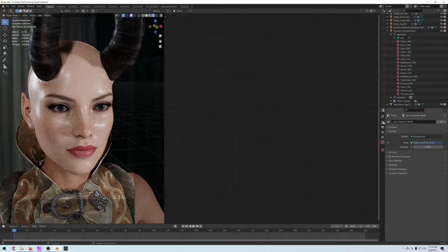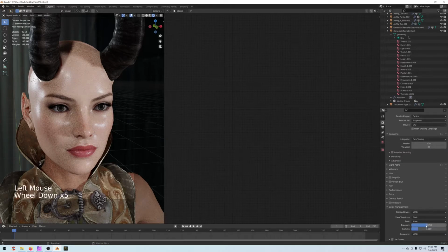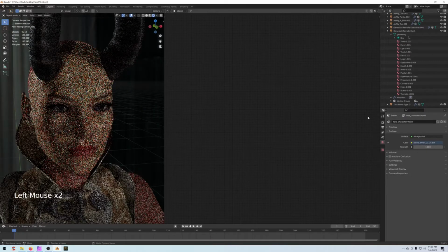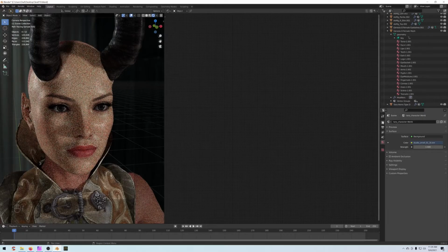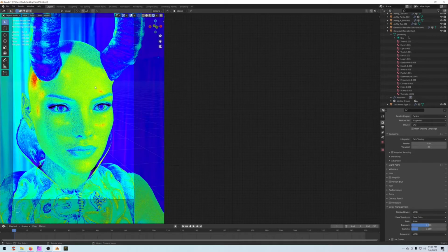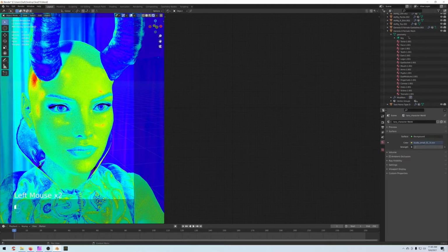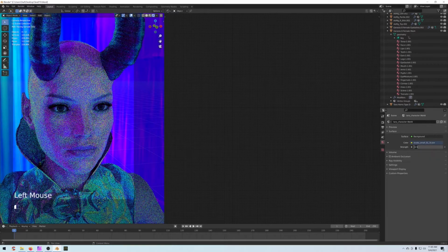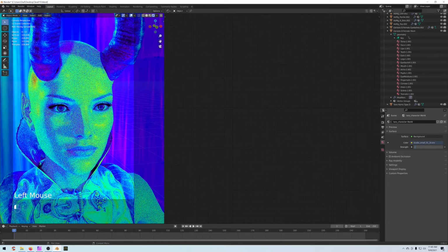And actually, since we're here, we'll do it with the lights this time. Set that back to 0. And go to the world lights. Set that down. And that looks pretty close. And let's switch this over to false color. And see these red spots, that means you're really getting too much light. So we'll change that to 0.5, maybe too low. Yep. 0.85.